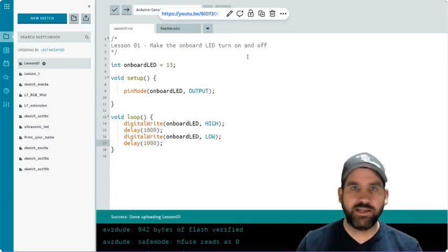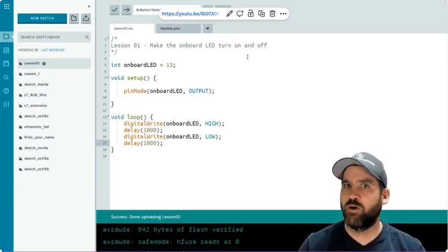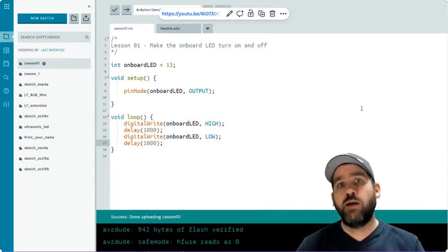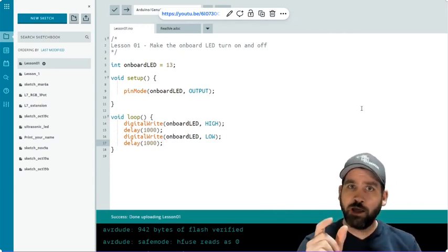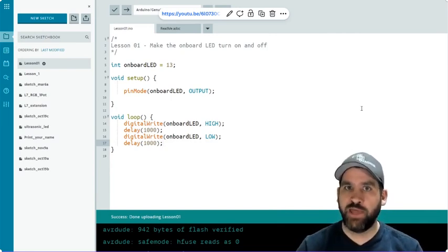And then in some of the lessons, I'm going to go a step further, and I'm also going to throw a challenge at you. Something that's got a little bit more oomph to it that might take you a little longer to figure out. For lesson 1 extension, I want you to set it up so your LED is on for 1 second, off for half of a second, and then just have it loop that blinking pattern.